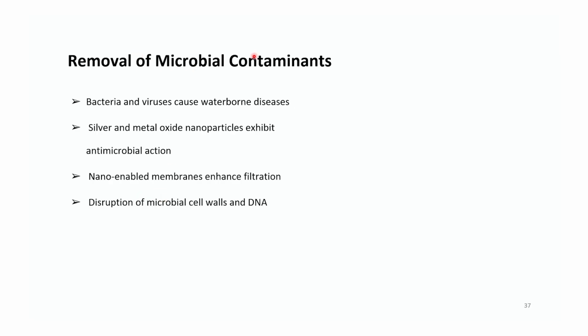The removal of microbial contaminants. Bacteria and viruses also cause waterborne diseases, like I've already told you. The membranes you've been using for water purification can result in fouling, and they can be highly expensive. So we need a sustainable and cost-effective solution to this. Silver and metal oxide nanoparticles exhibit antimicrobial action. Nano-enabled membranes will enhance the filtration process, and then disruption of microbial cell walls and DNA.